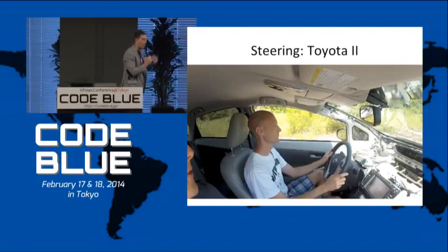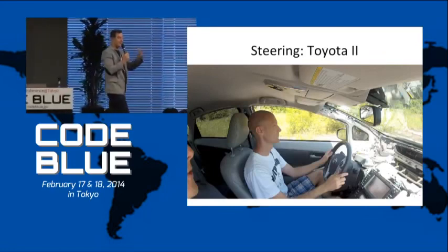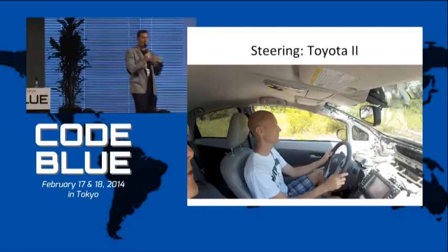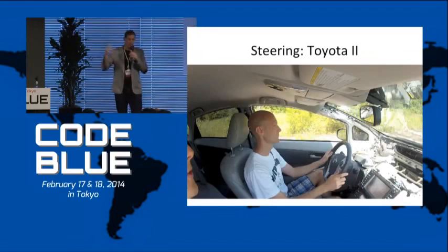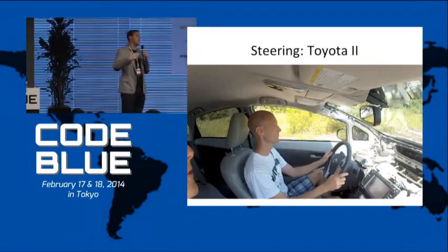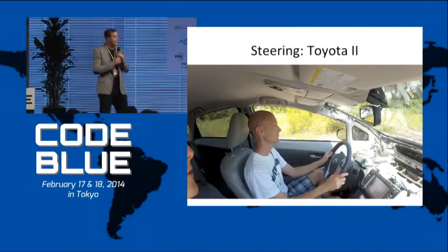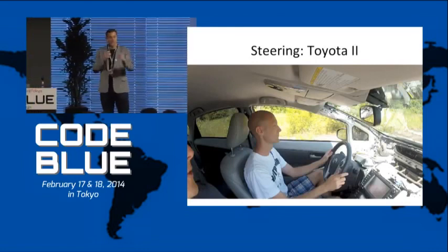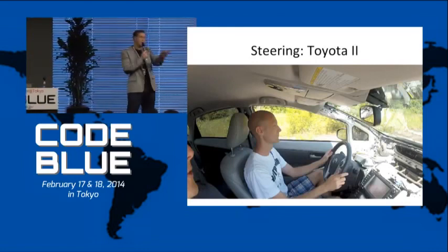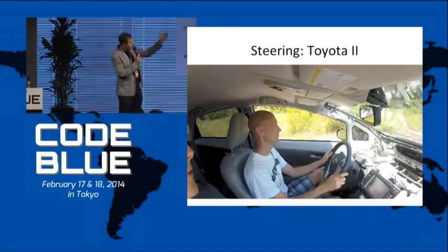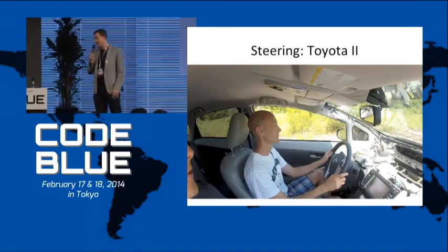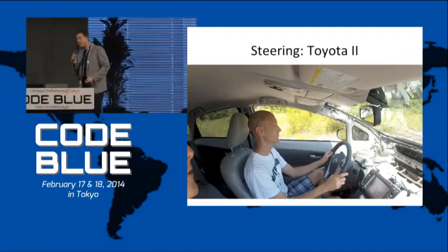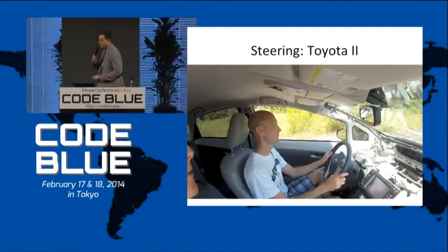So we just kept on pumping messages onto the CAN bus saying, hey, we're parallel parking itself. Hey, we're in reverse. And then we would flood it with a speed that it didn't know. And you would see the wheel turn after a beep. So what would happen is we would flood the network with a speed it didn't know. Some computer would go offline. The moment that computer went offline, we would send our message to turn the wheel, and pandemonium ensues. Right? So there are safety mechanisms, but at the same time, you can also trick them.